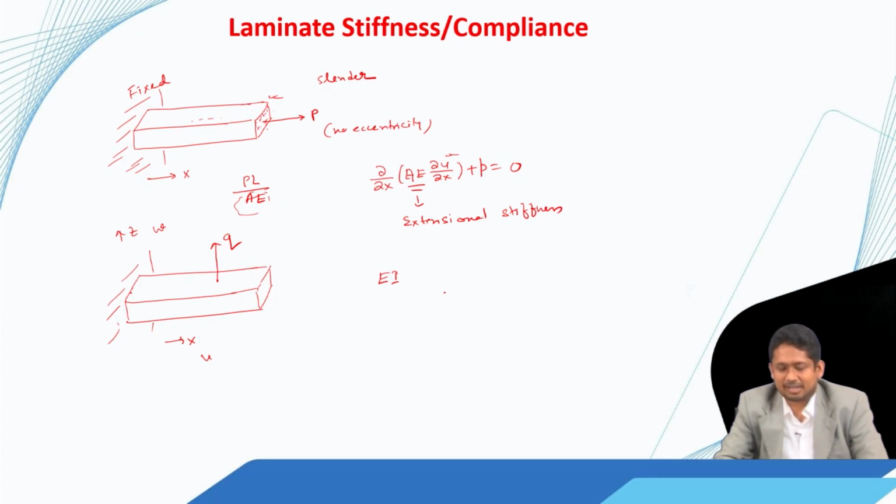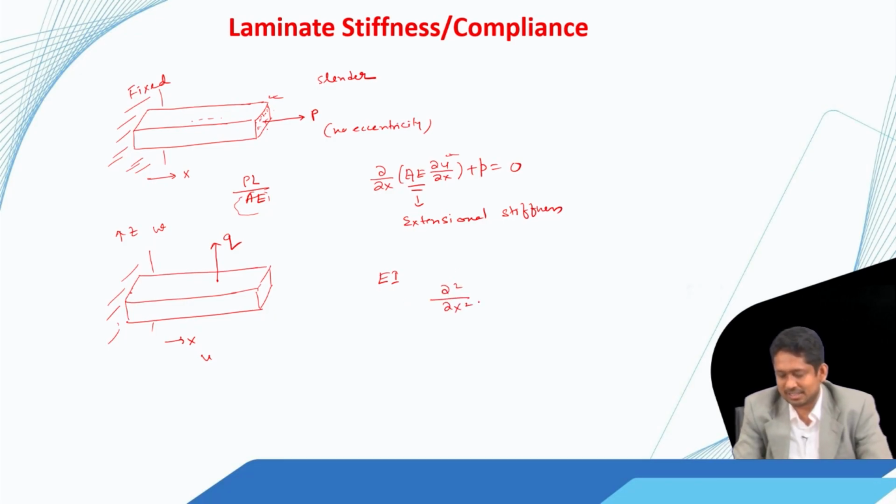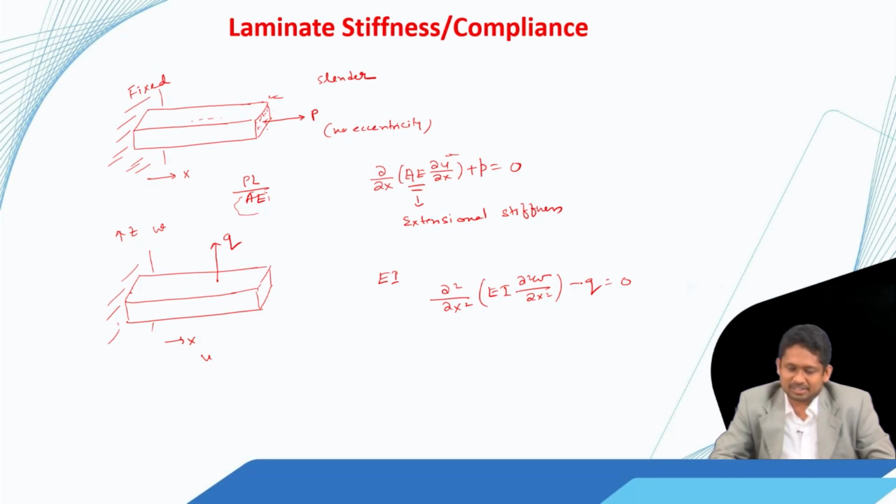That basically comes from the Euler-Bernoulli beam theory, and based on that we reduce this entire 3 dimensional problem to a 1 dimensional problem, which gives a governing differential equation like this. So, with all these things, what we are doing is we are making some kinematic assumptions, and with those kinematic assumptions we integrate some properties across the thickness, sometimes across the width also in these cases,